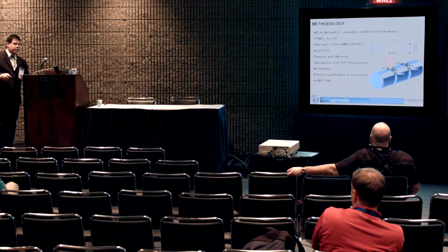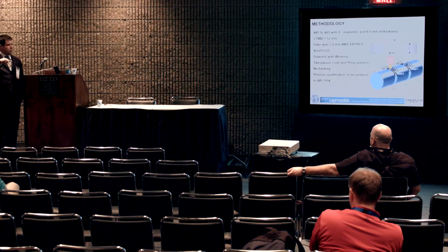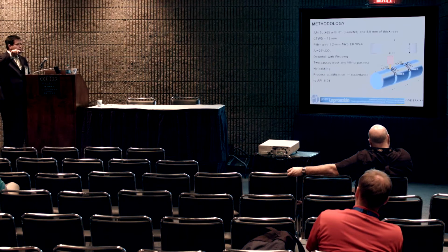Someone again may say, okay, that's not good. You should have used, I don't know, 22, 25 perhaps. But the idea is to use a small amount of deposit material to go faster, to go as fast as we could. And 3 millimeters of root opening.